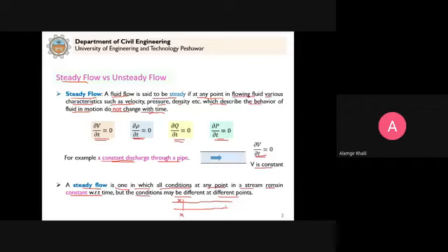steady flow here. But let's say at any other far point here, you consider another section, let's say YY. At this YY, it is possible that the discharge will not be the same as at XX, because there could be some outflow, or, as you already see in streams, we have either water adding to the stream or leaving the stream. So the discharge here will be different than here. It doesn't mean that this is unsteady flow. We just take one section at any point.